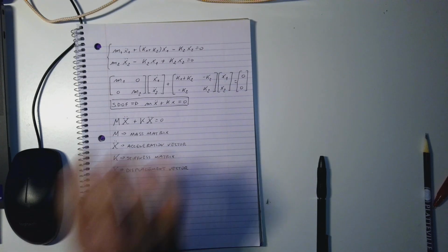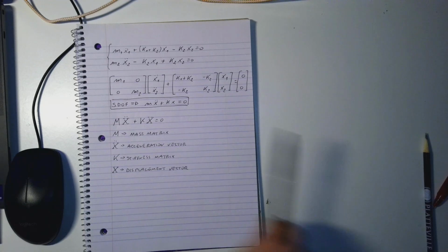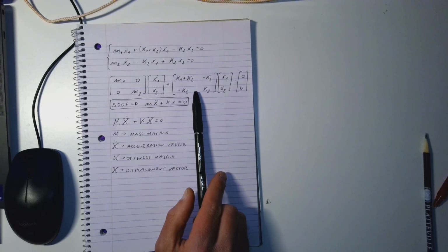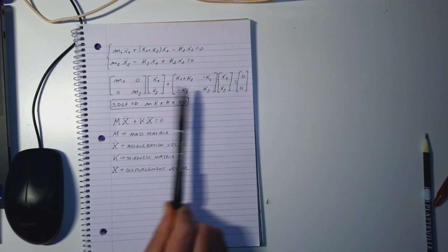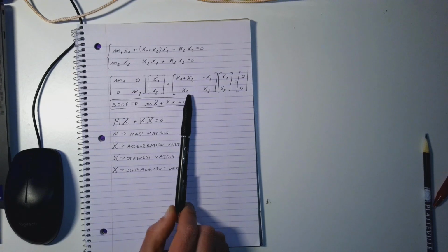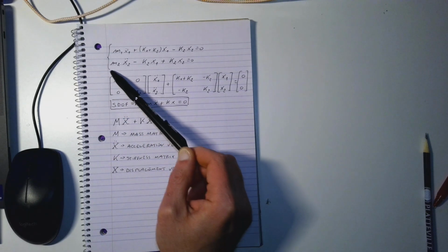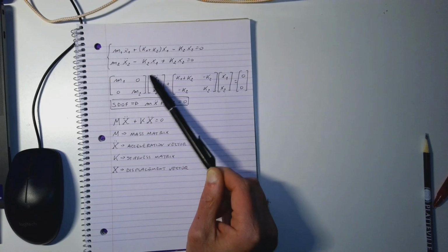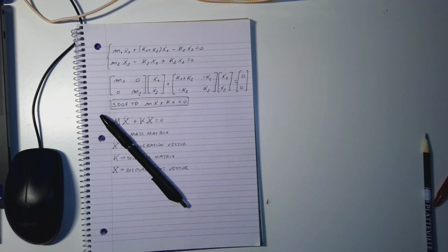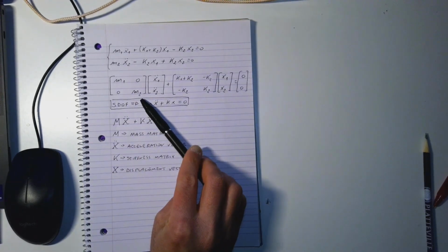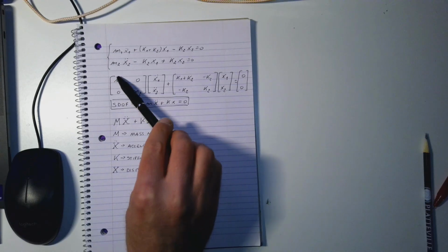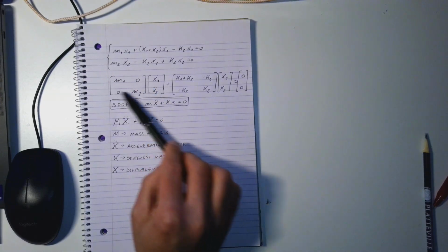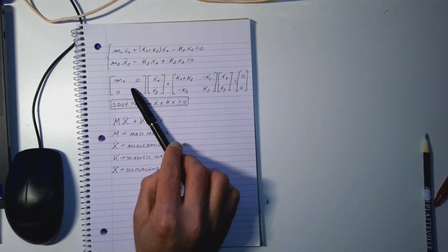So what do we have to do? We have to look at these 2 matrices, the mass matrix and the stiffness matrix. So what do we have to check? We have to check that these 2 matrices are symmetric. Symmetric means that when we look at the principal diagonal, whatever we have above and below must be symmetric. Which means in this case, when we look at the principal diagonal m1, m2, above here we have 0, here we also have 0, so it means this is a symmetric matrix.